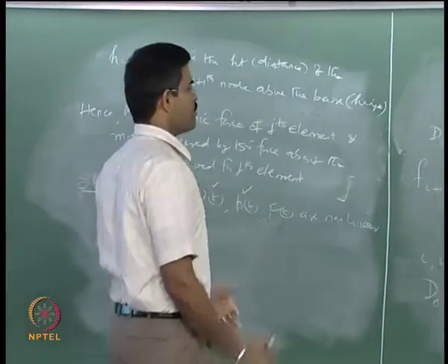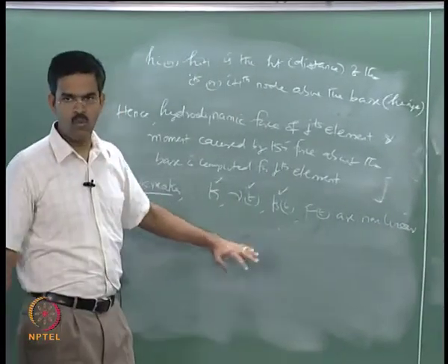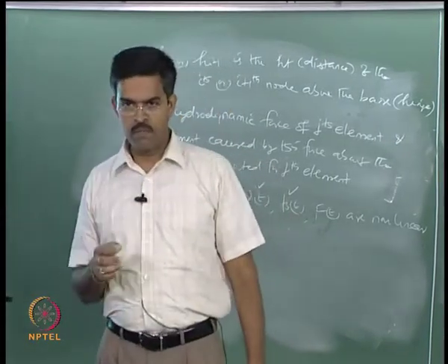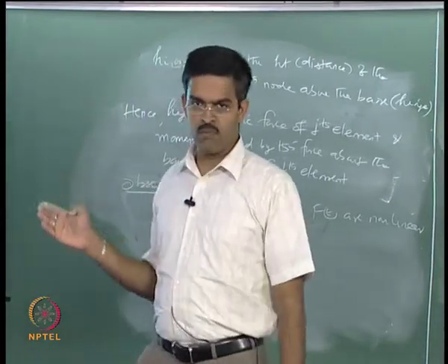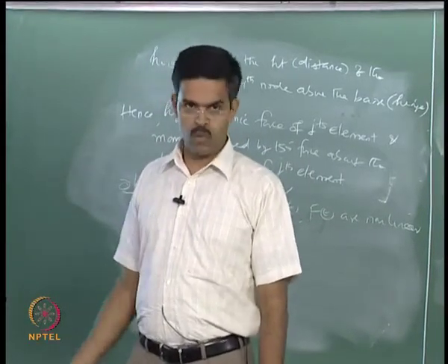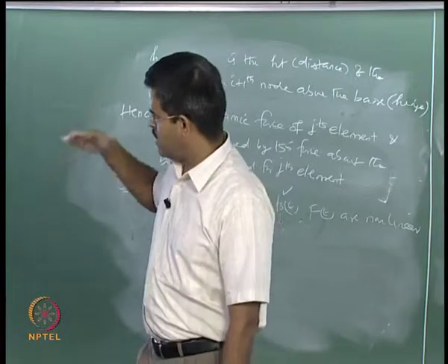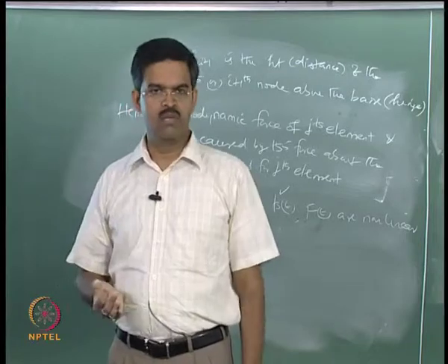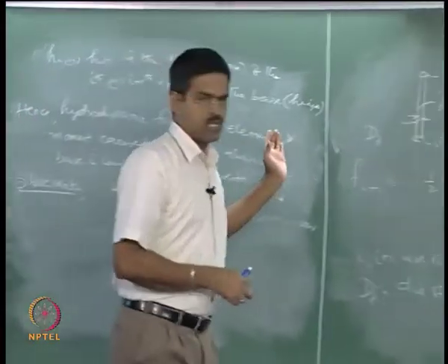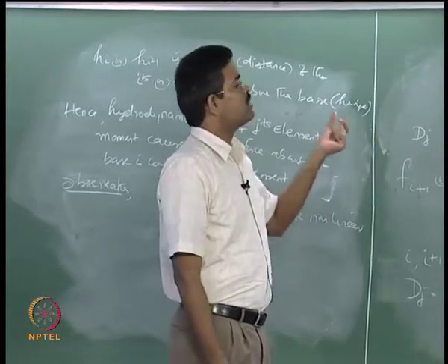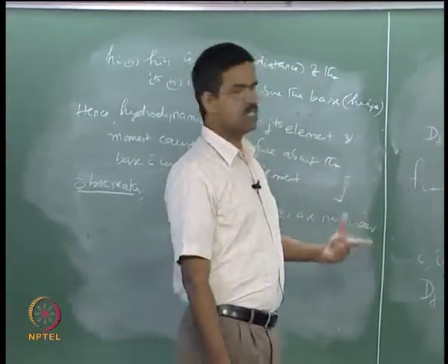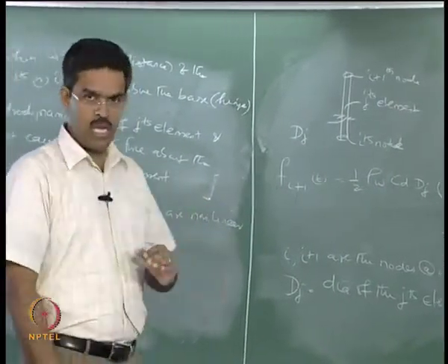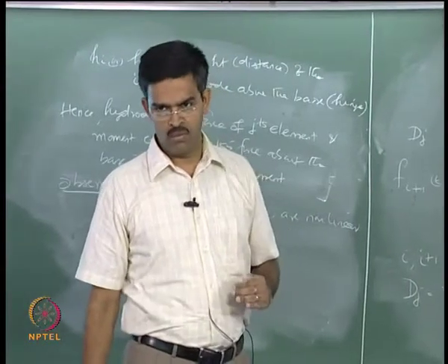If you have any difficulty in formulation of the problem till here, please let me know how we have formulated the whole problem. We started with an idealized tower model like this. We picked up the degree of freedom as rotation at the base. This is one of the approaches. We subdivided the tower and the deck, of course, at different number of nodes, and we wrote the equation of motion, rearranged them, and then we found out each and every term separately. Then we understand hypothetically and mathematically how to compute the equation of motion or f of t at any node I want or any member I want.